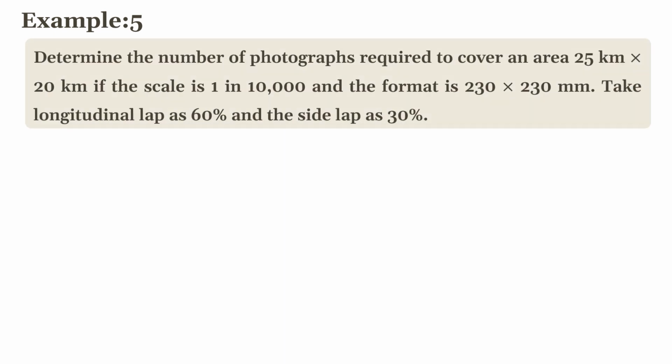Another example, determine the number of photographs required to cover an area 25 km by 20 km. The scale is 1 in 10,000 and the format is 230 by 230 mm. Take the longitudinal lap as 60% and the side lap as 30%.